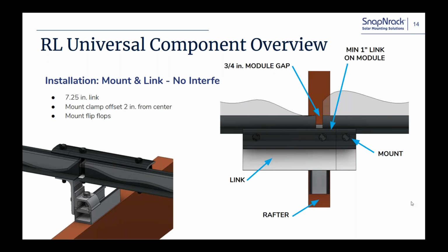Once you get the skirt down on a normal pitch roof, or once all the flashings, flash tracks, and skirt are installed, it's ready for modules. So you'll come back, everybody bounce off the roof, grab some water, and then start pulling the panels off and prepping them out. You can have one guy prep out the modules and two guys on the roof installing. Typically they'll just call down and say they want a negative up, negative on the right, positive on the right, whatever kind of install you have: landscape, portrait, mixed orientation, whatever it is.